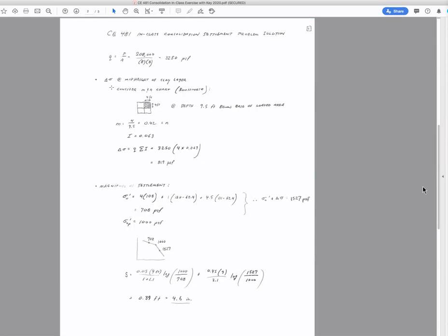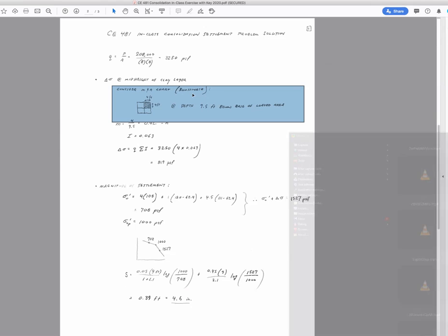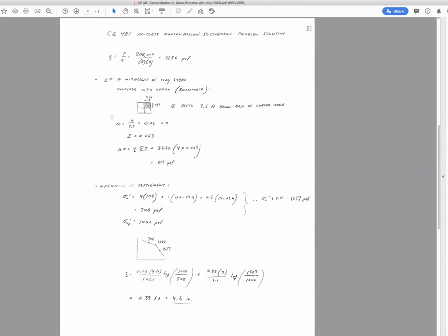And in looking at the M&N chart, we need to consider 9.5 foot below the base of the foundation, which takes us down to that mid-height of the clay. And it's the Boussinesq chart, which I'm utilizing here, which gives you the stress distribution at the corner of a foundation. The problem is requesting under the center. So we need to come up with a little foundation over here and then multiply the effect of that by 4. So M is going to be 4 over Z, 9.5, and that's 0.42.